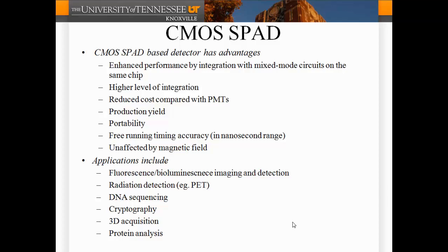So under very high voltage, if a photon is incident in the depletion region of this photodiode, it will trigger the impact ionization and avalanche breakdown, which will be detected by the current produced by the photodiode.